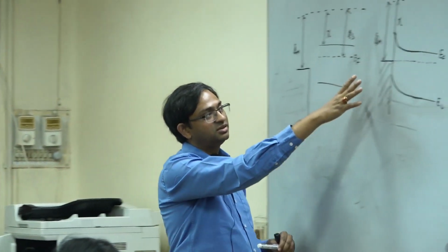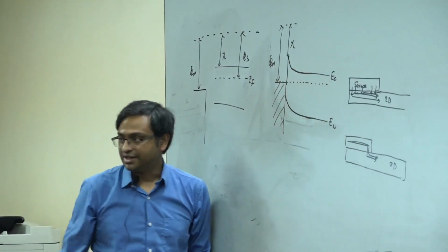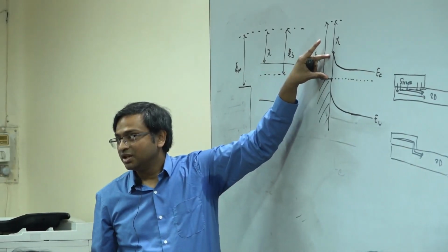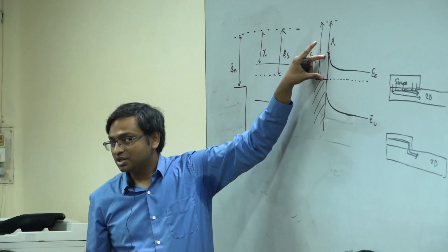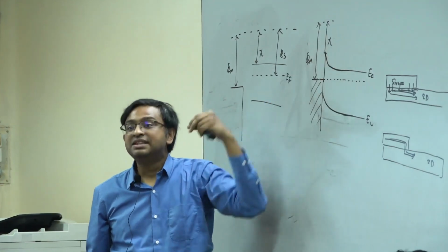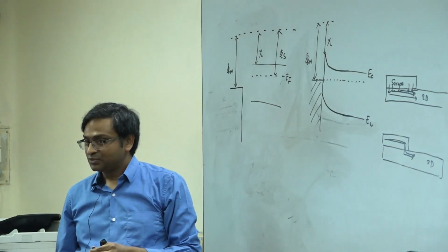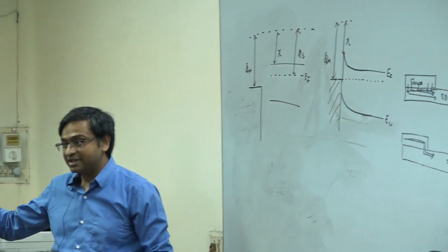Right? Now you see, there is a problem in this junction, because we want the electrons from here to come into the channel, right? But will they be able to come? Because there is a barrier, potential barrier, correct? And this is what we call the Schottky barrier, right? So therefore, the expression that we derive for the contact resistance, true for ohmic contacts, not true for this, because now the carriers cannot easily come in. So contact resistance is going to increase or decrease?